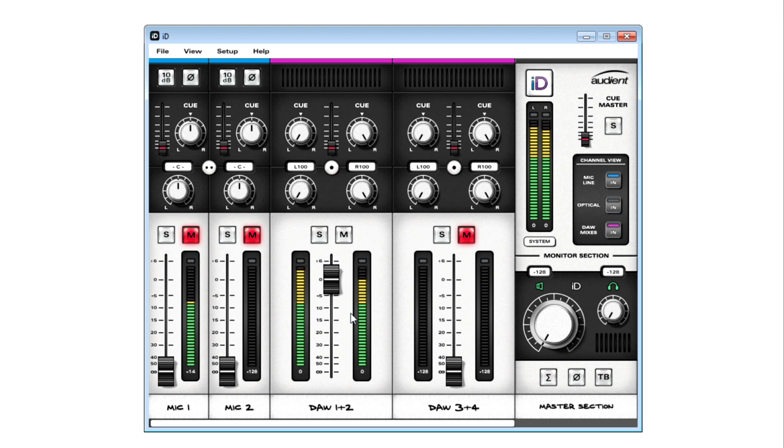All right, see that? See how it's like super close to being at the maximum level, and there's a lot of yellow bars now compared to when I had it at -20. Well, why is that? It's because the signal is going through this little matrix of a program, and at its default setting of 0, it's nearly clipping the output converter. And what does that mean? That means that this is going to be the setting that I'll have it at on the final output gain.